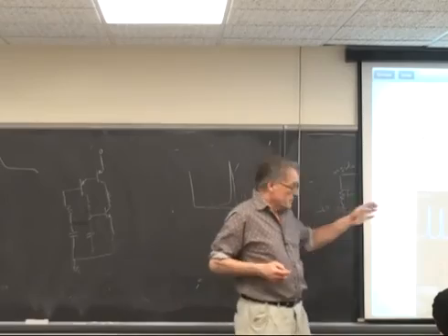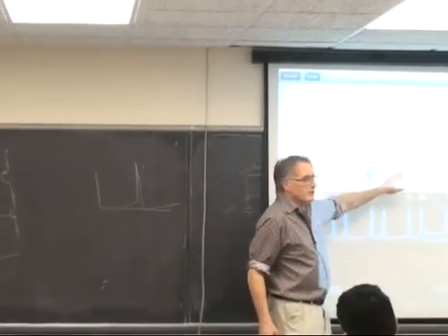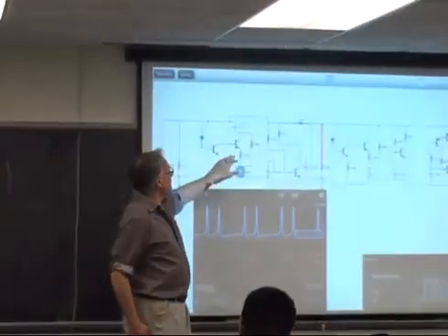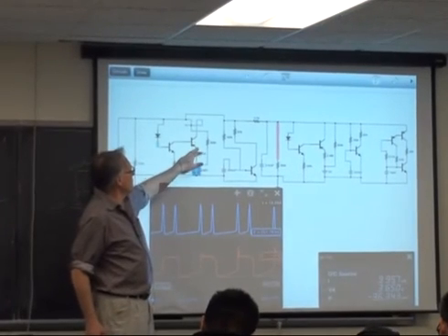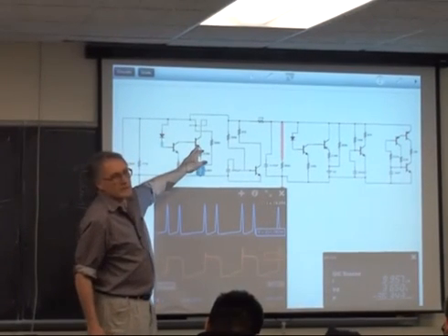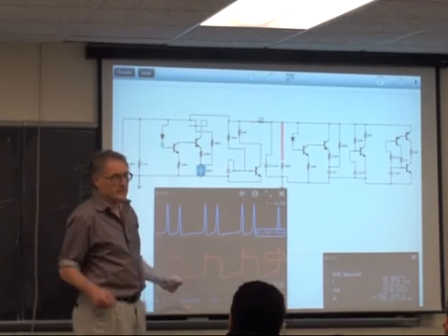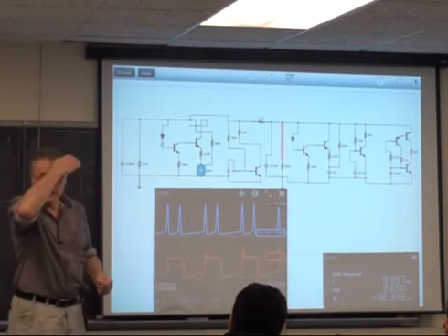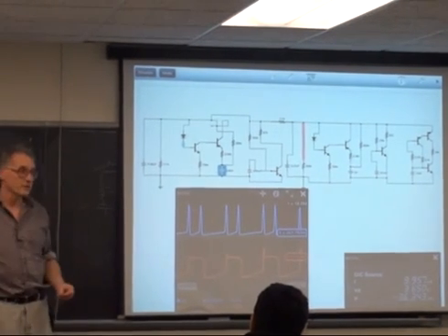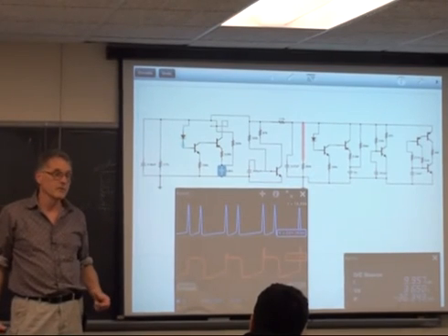It uses Kirchhoff's voltage and current laws to set up the differential equations, and then the static nonlinearities of the transistors and the diodes are modeled in some specific way, which may be more or less realistic, depending on the simulator.